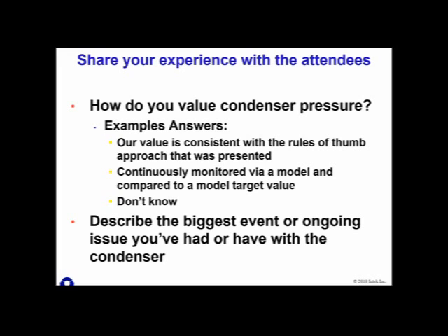What I'm asking is for you to describe the biggest event or ongoing issue that you've had with your condenser. So if it's, I don't know, air in-leakage or fouling, or perhaps it's not related to those, maybe it's related to condensate chemistry. Maybe you're feeding a lot of hydrazine in, trying to combat dissolved oxygen. That may be an issue that we can address.